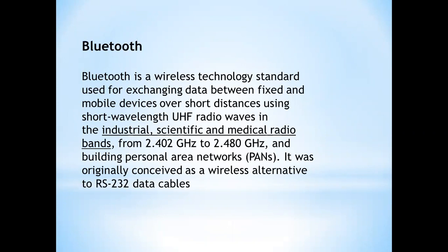Designed to operate in the noisy frequency environment, the Bluetooth radio uses a fast acknowledgement and frequency hopping scheme to make the link more reliable. The Bluetooth radio module operates in the unlicensed ISM band at 2.4 GHz and avoids interference from other signals by hopping to a new frequency after transmitting or receiving a packet. Compared with other systems in the same frequency band, the Bluetooth radio hops faster and uses shorter packets.